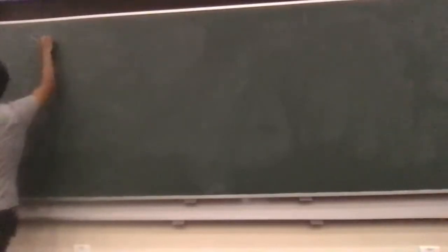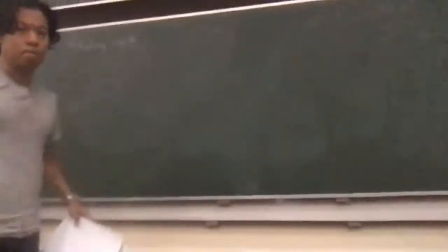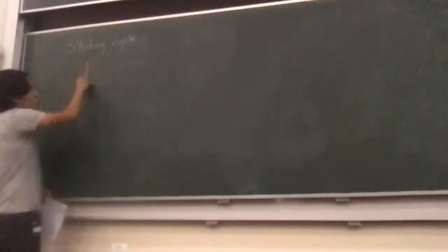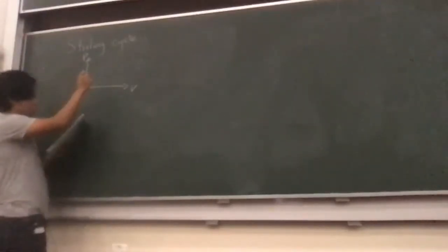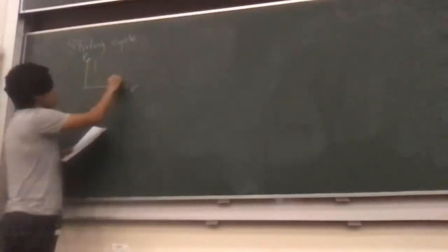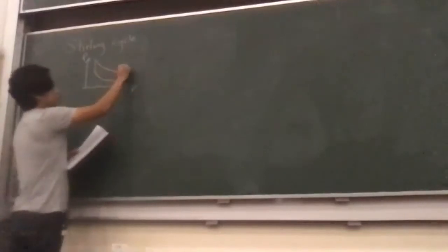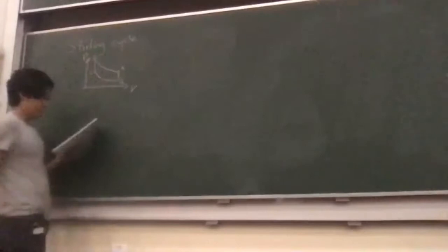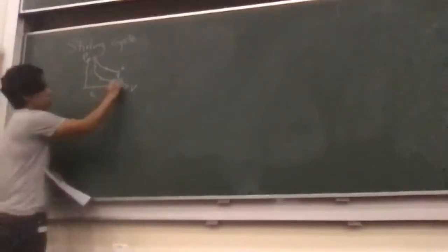Okay, so the first one I'll do is the Stirling engine, or Stirling cycle, whatever you call it. Draw the PV diagram first. Here you have two isovolumetric processes connected by two isothermal processes. Let's call this A, B, C, D, and it goes around this way. I'll call this the lower volume and the higher volume, and the pressures are just labeled with whichever point they correspond to.